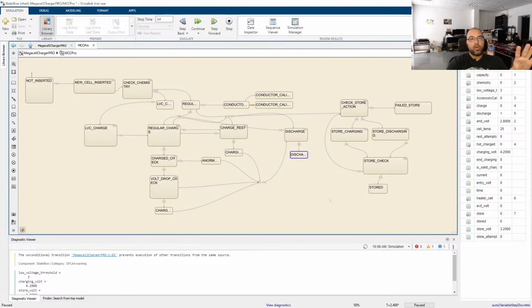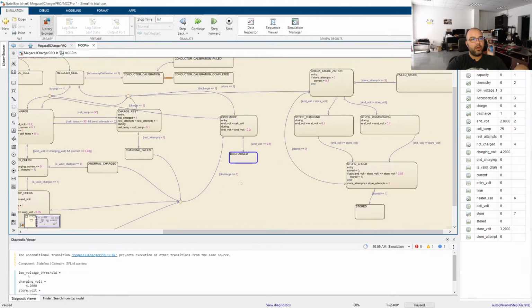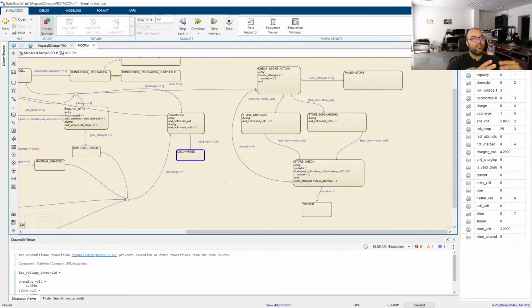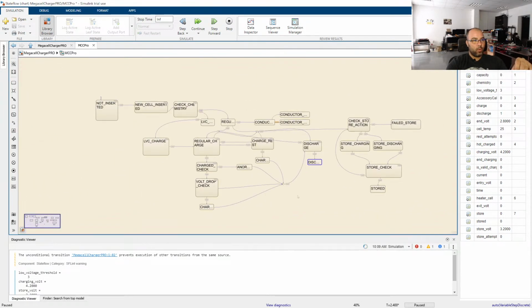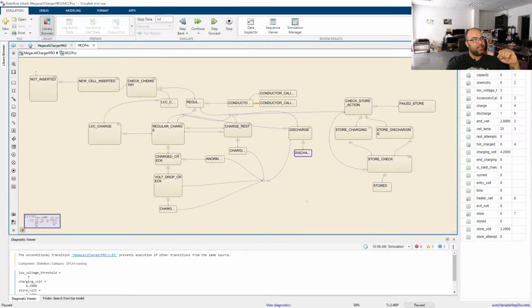MegaCell Monitor supports up to 80 chargers per device right now, which is enough, it's impressive. But if you aim for 1,000 devices, for example, that will make it a bit difficult polling data from each device, like sending requests and then waiting for data back. Instead of that, you will communicate directly with the database. You don't have to communicate with the charger. You just set something in the database, the charger reads it when it's regularly polling information from it, and this way we make the monitoring software much simpler to use.